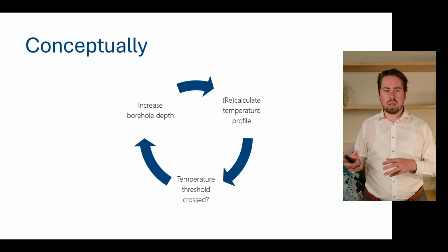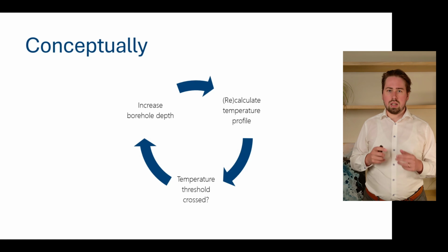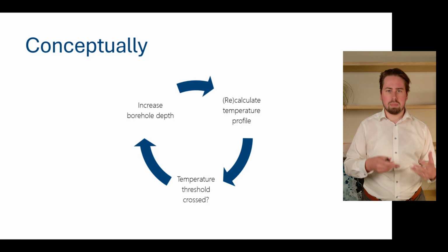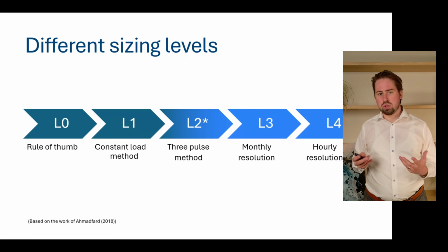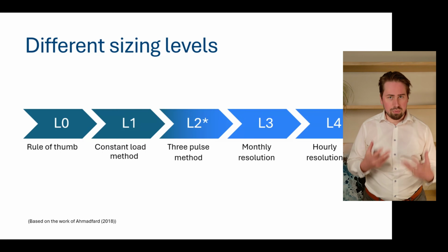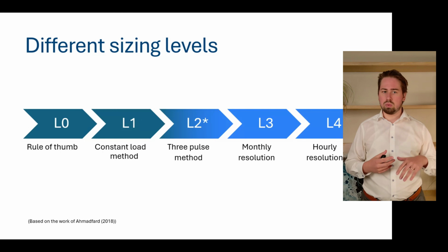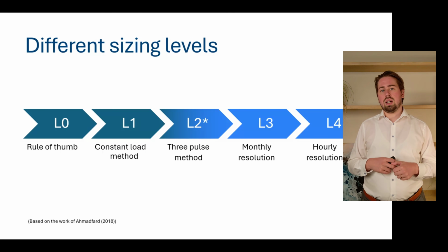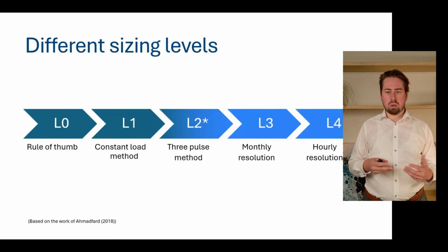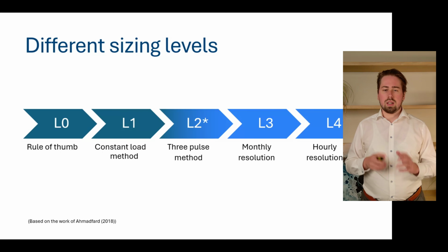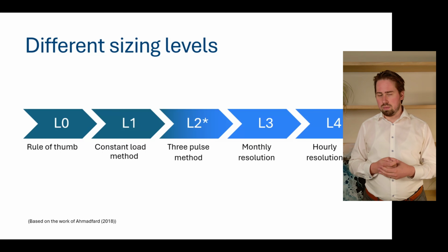But before we look at some examples in GHEtool, let us talk about the different ways you can do this basically. Because in literature there are 5 different levels of sizing accuracy for geothermal bore fields. Starting with the L0 method, which are rule of thumb ways to cope with this problem, all the way up to sizing with hourly resolution. Now, let us go over them in a little bit of detail.